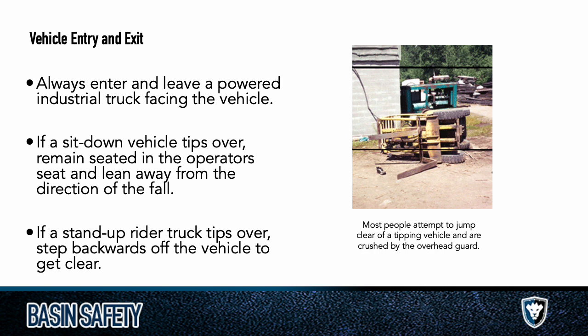That is where a lot of fatalities happen, is that people, again, aren't belted, fall outside, and are crushed by the forklift. These are not light pieces of equipment. They have some weight to them, and they're very unforgiving. So if you're riding one that stands up, then you can just jump off as it's tipping over. Again, the best option here is don't put yourself in a situation where your equipment's going to tip over. Drive low and slow, low and slow.